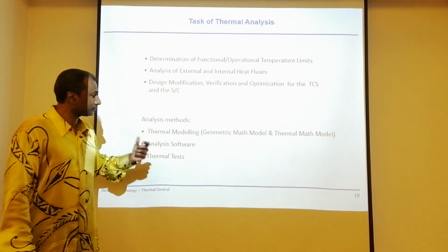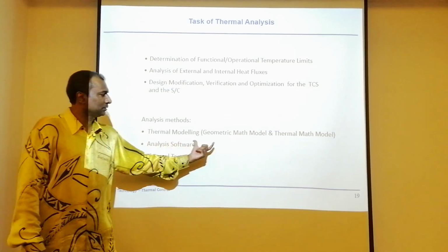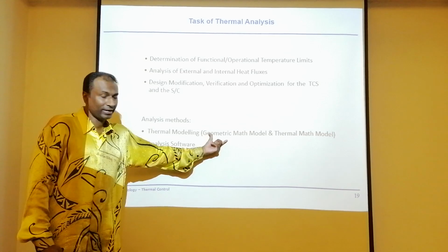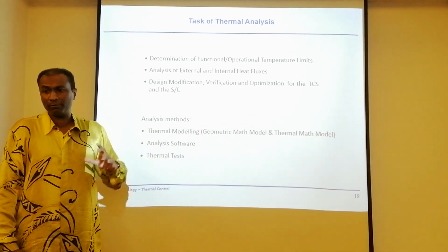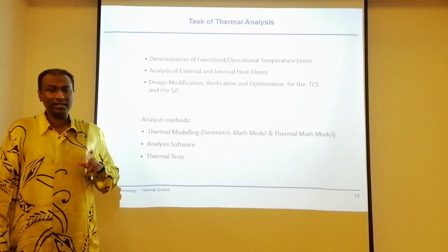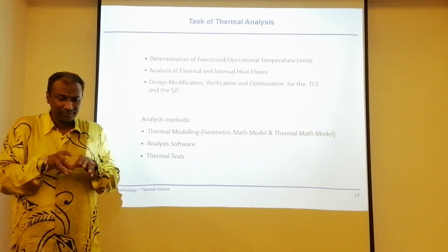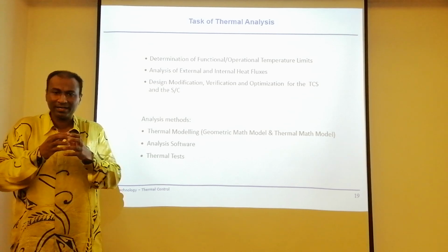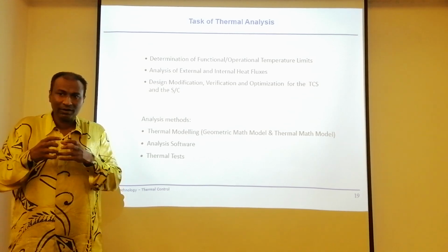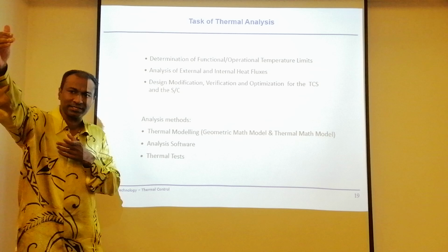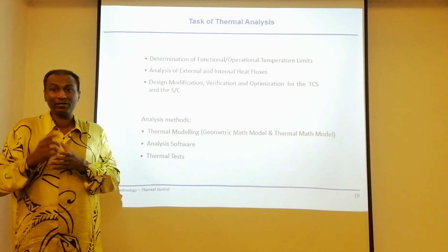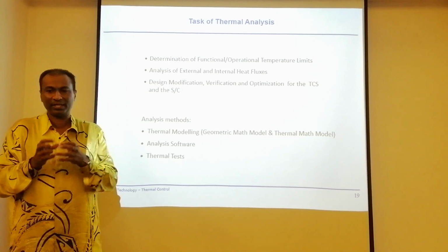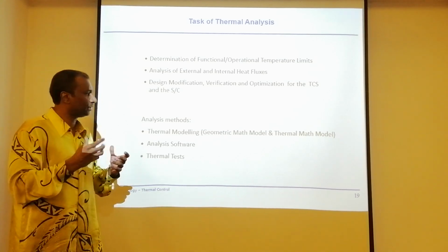Analysis methods: thermal modeling, geometric math model, thermal math model. The geometric mathematical model is very complex. It can only be done numerically, because for each and every component of the satellite you need to generate its geometry and then see how this geometry is looking at the sun, and then start estimating the actual temperature generated at that particular component.